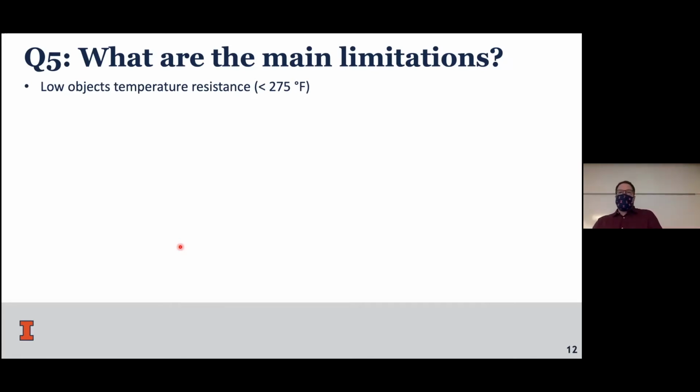I'm not sure of the volume exactly, but usually they're expensive to rent. The bigger you go, the more compliance you have, so the more your frame is going to get bent when you print. Then you usually lose a lot of accuracy once you go bigger. So if you want a testing frame, for example, with bigger objects, you have to increase your frame size by a lot, and it costs you.